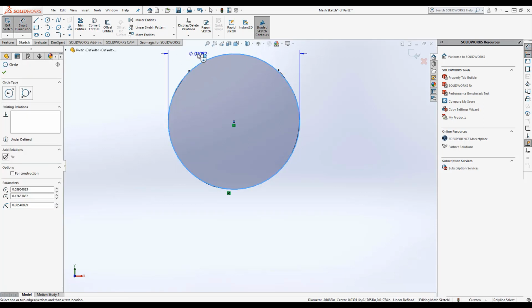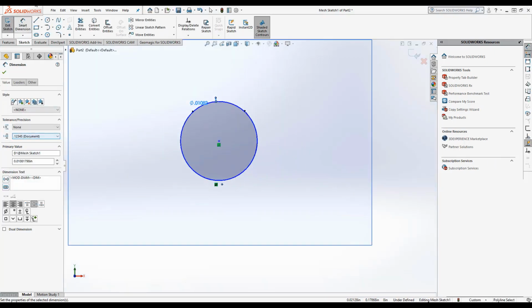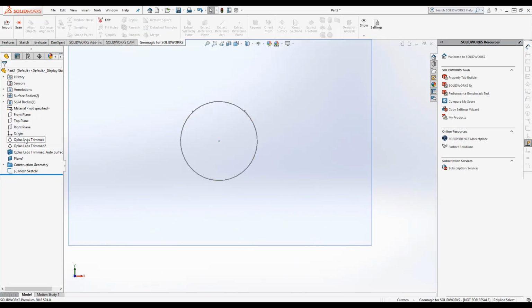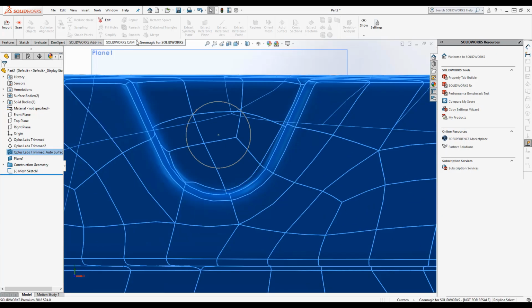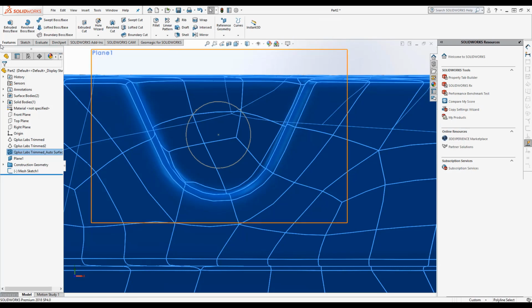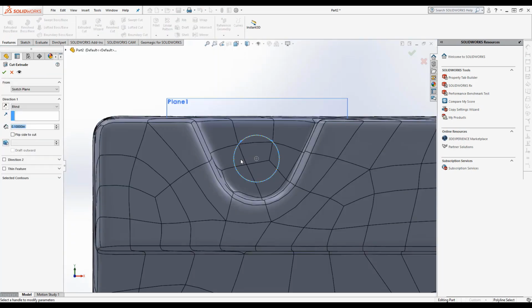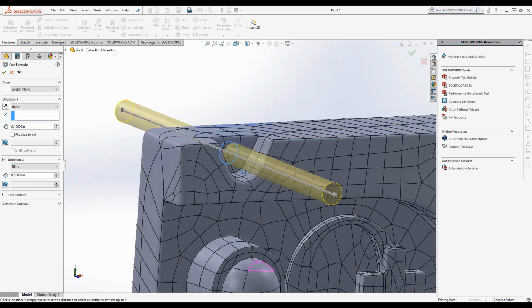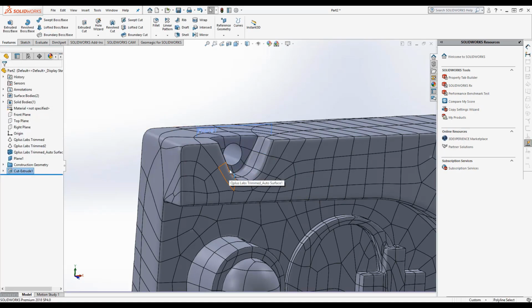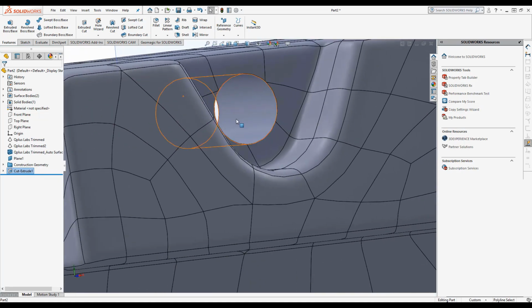For the purpose of this webinar, we'll save this. So I'll exit my sketch. And I'll open up my auto surface. And I'll go into SOLIDWORKS features now. Extrude. I'll highlight my mesh and I'll go into extrude cut. And I'll say both directions and apply. And now we have our first machine surface that we can use in an assembly constraint.